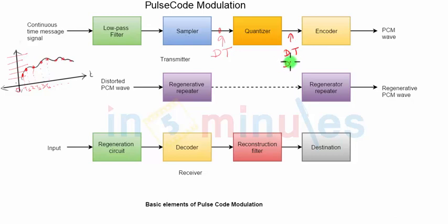At the same time, it is discretized in amplitude domain also. But the output amplitudes may still be represented in the form of an analog signal. So now how do we give the perfect digital nature to these analog fixed values which we have at the output of the quantizer? These analog fixed values are now represented in the form of ones and zeros with the help of the encoder. Hence, at the output of the quantizer, we will be assigning fixed values to various samples which are coming at the input of the quantizer. These fixed values are also represented in the form of ones and zeros, and that gives us the perfect digital nature to our signal.